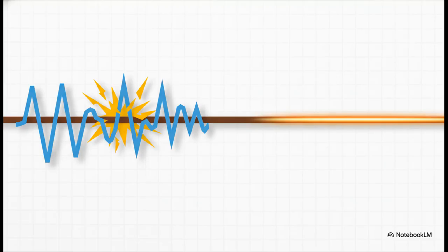See, this noise can literally jump onto our 0 to 5 volt signal, distorting the message and making it totally unreliable. On top of that, if you try to send this signal down a really long cable, the voltage can actually drop along the way. That 2.5 volts that meant half full might show up as 2.4 volts at the other end. Your reading is now wrong. The message gets weaker the farther it travels.